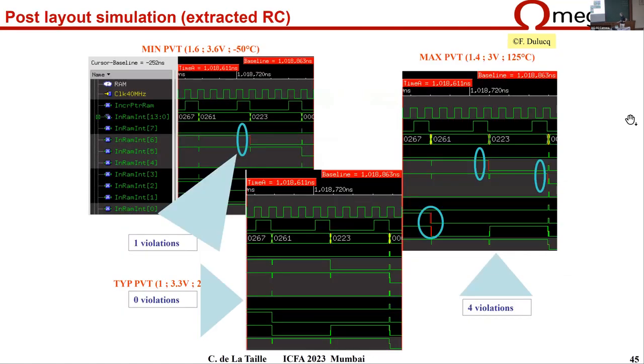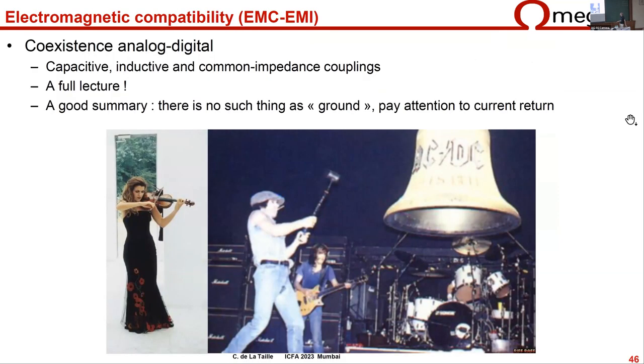And of course, once again, I don't want to go into all that, just to give you a flavor of what is going on inside all these chips and why so many people are spending so much time to make these things work, because they get more and more complicated. One thing that we have, especially in calorimetry and in timing, probably more acutely than in pixels, is that there is a lot of digital activity very close to a very sensitive analog front end. So you try to get your small signal, and then you get a lot of noise around, and the digital activity, which is very synchronous, so everything is happening exactly at the same time, is inducing a lot of noise.